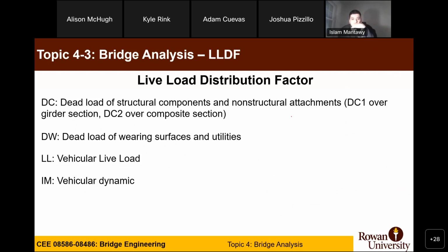You have the dead load of the structural components and the non-structural attachments. You also have the dead load of the wearing surfaces and utilities. And then the vehicular live load and the vehicular dynamic load. Those are some of the loads that we've been talking about in class the past couple weeks. Okay, thank you, Allison.